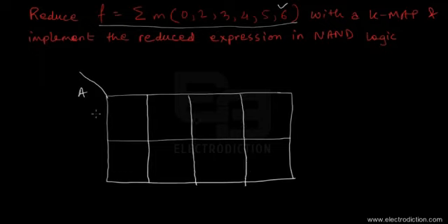Okay, so for the rows we'll have basically 2 values of the binary numbers, that's 0 and 1. And on the other hand, for the columns, we'll have double-digit binary numbers. So it'll be something like 0, 0, and then you'll have this one as 0, 1, and then again 1, 0, and 1, 1. Much like the examples that I previously showed you in the earlier tutorials. So we'll need 2 variables to designate such values of binary numbers. So we'll just keep the variables b and c for the designation of the columns.